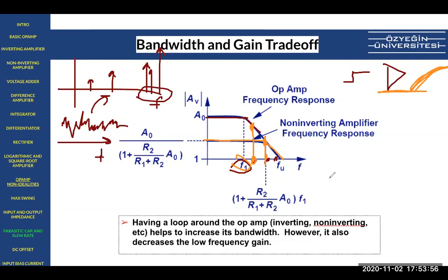This frequency is a function of some kind of time constant, 1 over RC. Always these cutoff frequencies are represented by 1 over RC. The cap charges, the cap discharges, that creates the poles and zeros. And here F1 is caused by a capacitance in your structure, deep down in your circuit. And this cap sees this equivalent R, and it creates this cutoff frequency. If F1 is small, that means the cap is big, right? If that cap is big, it takes a lot of time to charge, which makes sense because that's what this structure is saying.